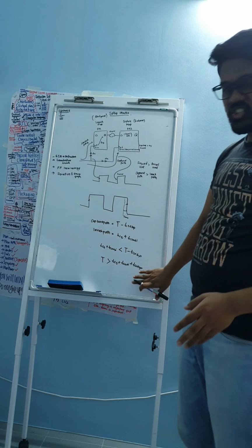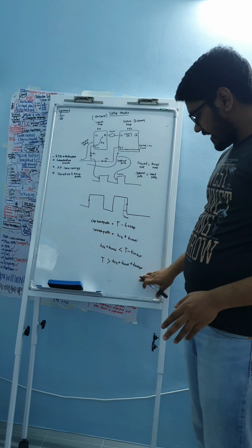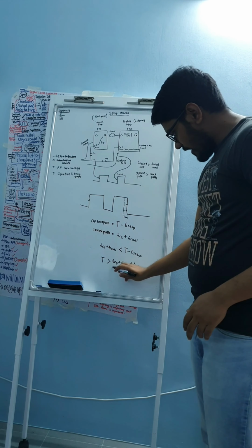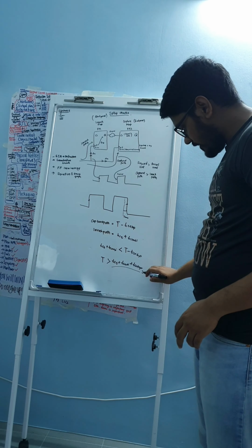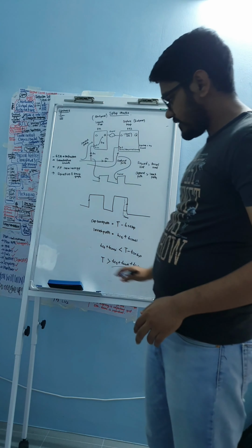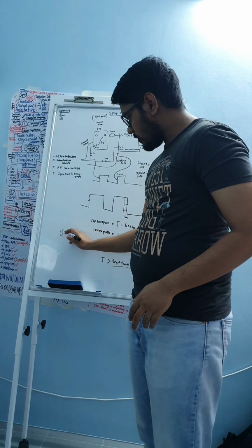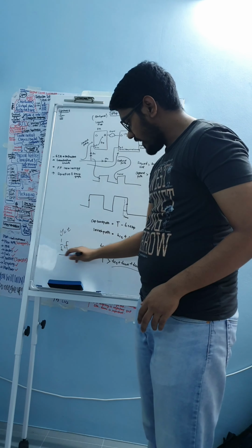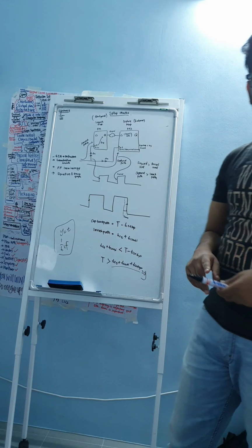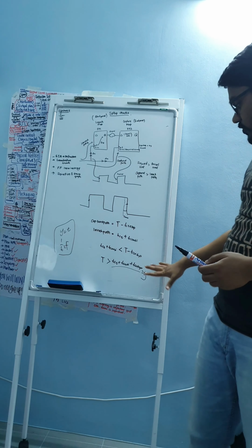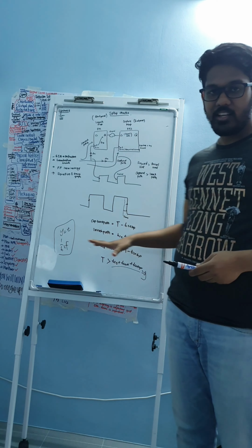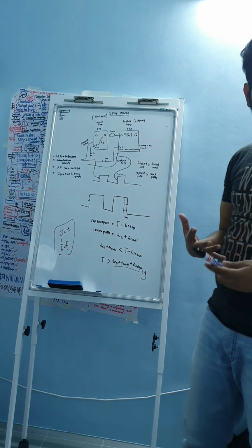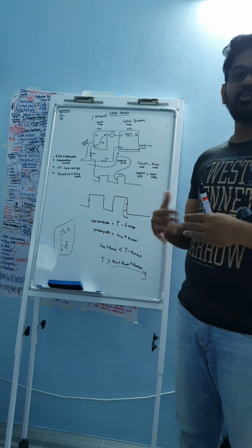Actually, by doing so, if you add up all these and then add up all this, which I put equals to Y, and this Y equals T, then 1 over T is your frequency, and this is going to be your maximum frequency. But it is not to be only one path. You can go for a critical path and try to evaluate.